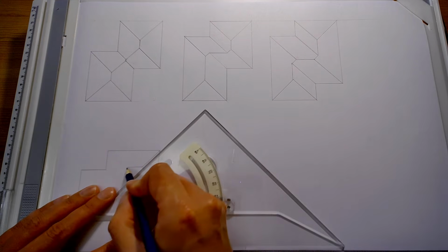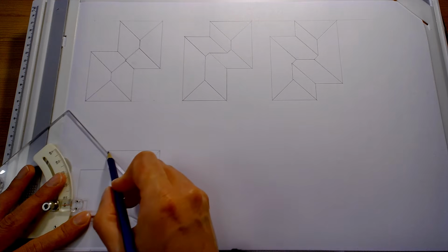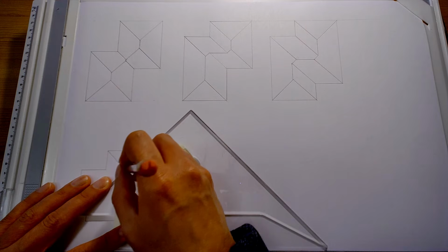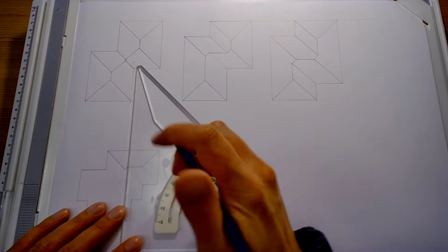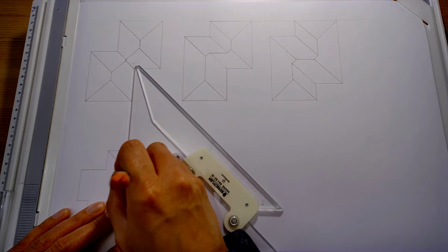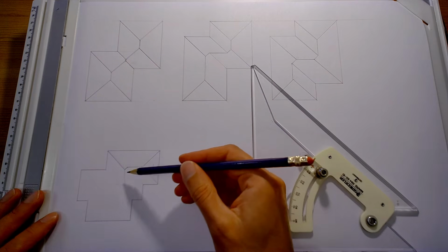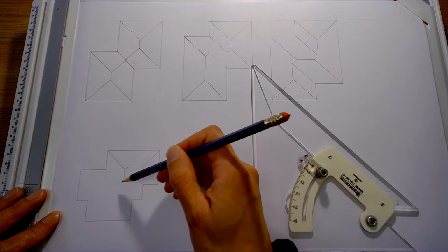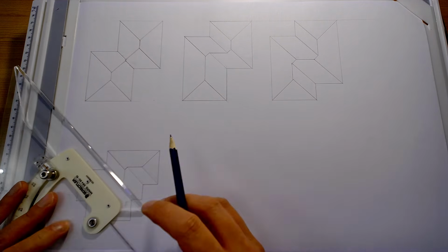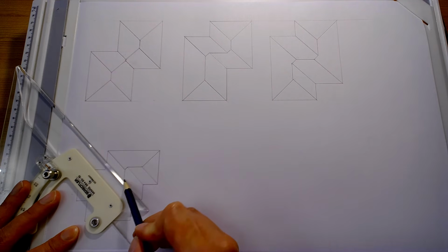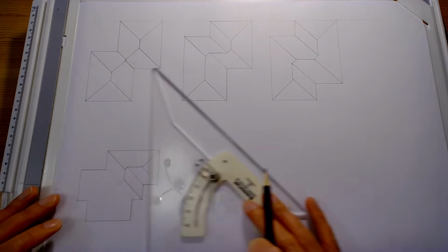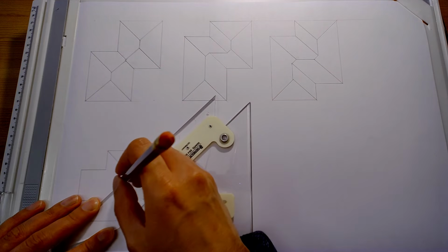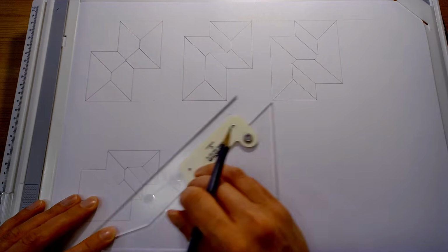Now 45-degree line there and a 45-degree line from this corner creates our new hip, which in turn creates a ridge coming along here. So again, we follow this ridge. It's going to reach this hip before it reaches anything else. So let's just draw that in. And from that point it has to go downwards. So we'll do a 45-degree line going down.